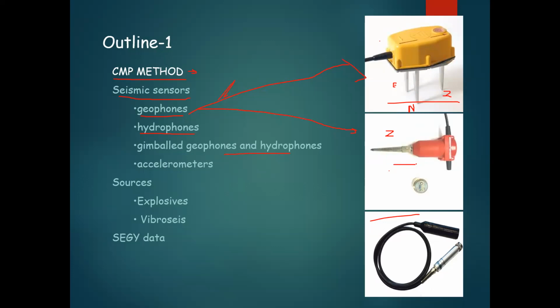Now the question is when and why we use independent geophones. Suppose you go to a place and the place is flat, so you can plant wired or connected geophones and there will be no problem. You can keep the geometry even. For a flat surface, you can plant geophones. Suppose I want to plant a geophone every 2 meters on a horizontal surface, I can do that easily with wired connection.